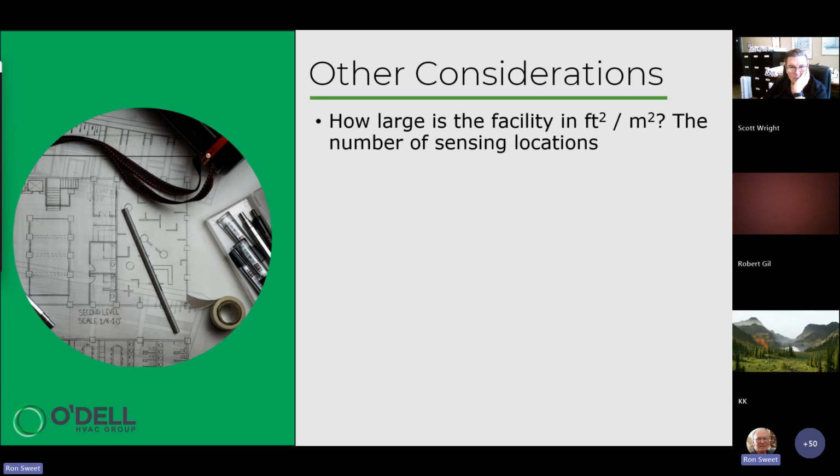And just about every gas detection system manufacturer in today's world has that capability of monitoring multiple sensors with one controller and enacting ventilation based on those sensors reporting back in real time the concentration of the target gas within the area that the sensors are installed.